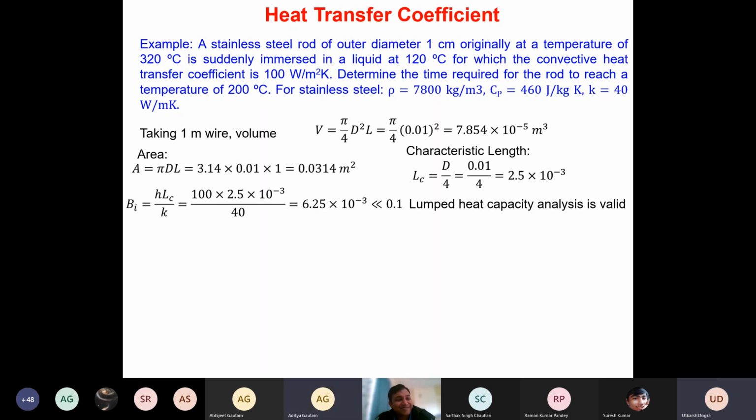Confidence was lacking. So in the ice ball, we assume that the whole ice ball is at 0 degrees Celsius, not in the negative. Because it's ice present at zero temperature, isn't it? So we are assuming that the temperature is not going to change and that the sensible heat is not there. Whatever heat is added is only going to reduce the size of the ice ball, but the temperature of the ice ball is not going to change. So there is no conduction taking place inside the ice ball.